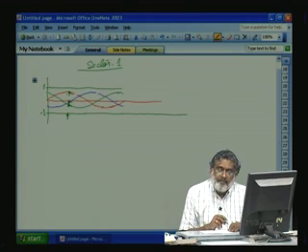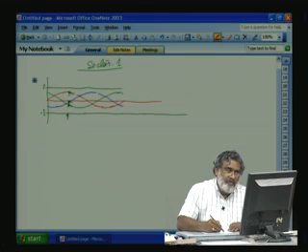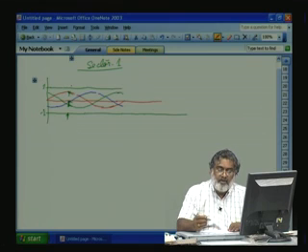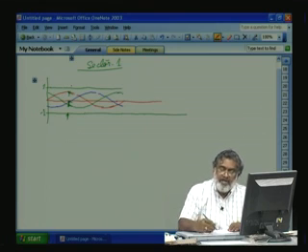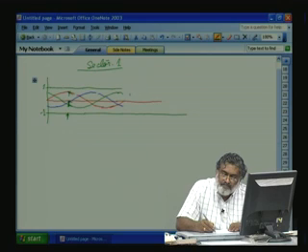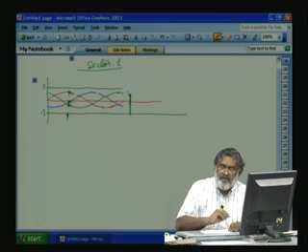When you sample it, let us say for a triangle waveform, as it moves from here to here, high frequency sine wave, high frequency triangle wave, till this point, sine is greater than the triangle for A phase. So, you will get a high signal here, after that it will be 0. Now, if you see the amplitude till that point, it will be here. This is the amplitude, A phase.